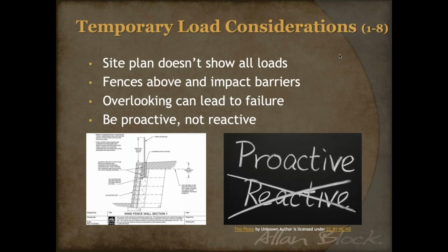The reason it's so important to consider this is that overlooking any of it can lead to failures of the wall. If you're not accounting for a surcharge that is temporarily above the wall, that wall might undergo some pressure or have some forces on it that weren't accounted for in the design, and that's an issue that we need to address early on. Like I said before, the biggest thing is to be proactive instead of reactive. So we're looking at where those loads might be and how we can address them early on and make sure that the wall is designed to accommodate any loads that come up in the lifetime of it. That's why it's so important.